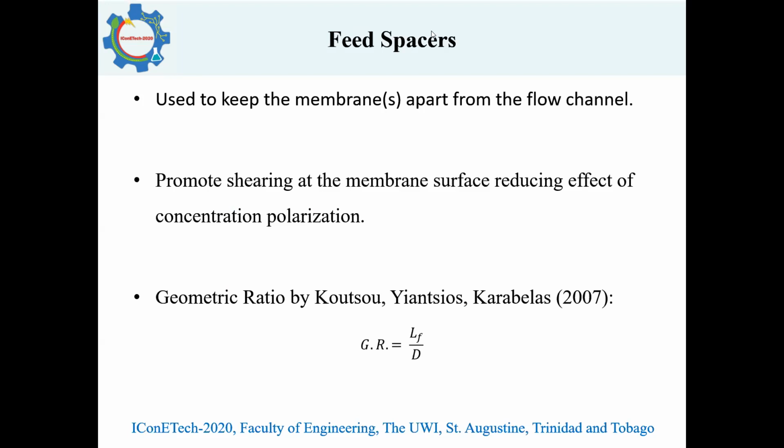To be able to model the concept of feed spacers, or the distance between feed spacers, we used the geometric ratio by Koutsou, Yiantsios, and Karabelas from 2007, which is defined as the distance between individual spacers and the diameter of the spacer. For ease of use, we assume that the diameter of the spacer is half the height of the membrane feed channel.